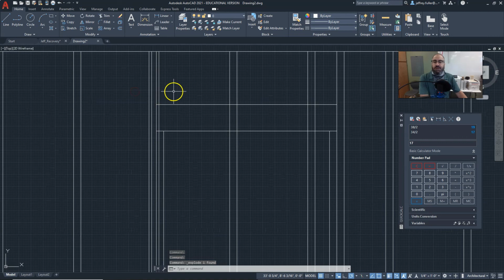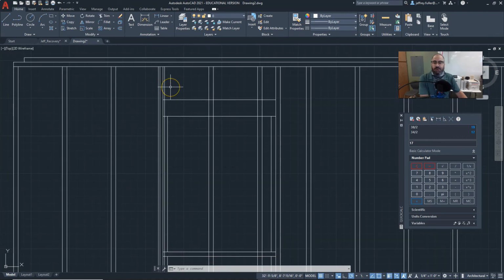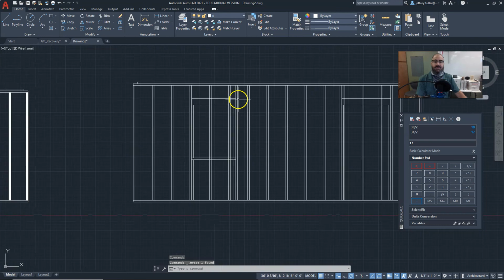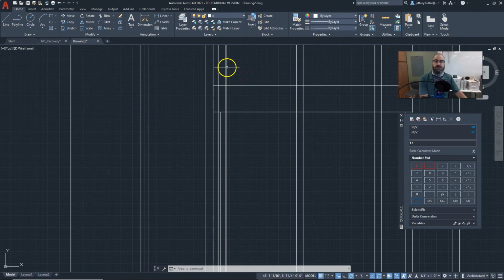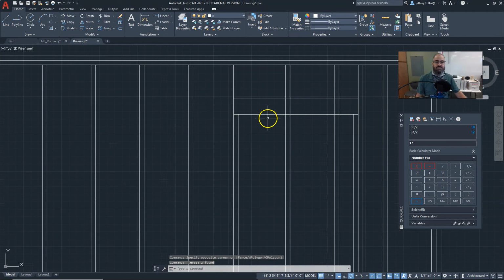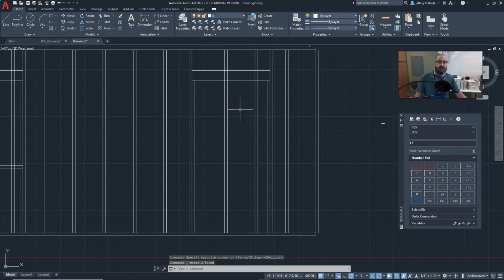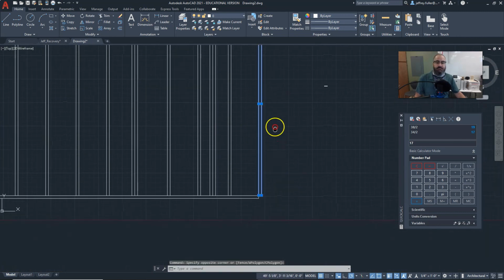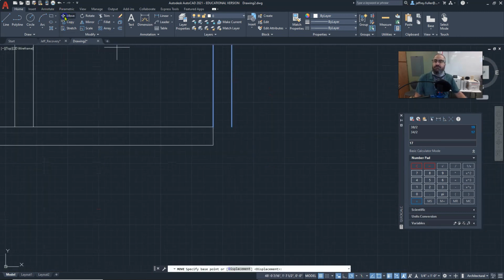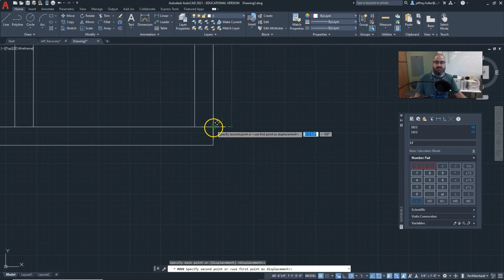All right, and in here I got to be real careful. Some of these overlapping studs I want to take a real close look at before I delete them. Okay, that one was overlapping, so I deleted it. Let's see if there are any other overlapping ones, maybe right here. This one is an overlapping stud. Okay, right there. All right, now there are some other studs that are in the way. This stud right here, I'm just going to select it, click the Move tool, select this as my base point, and then move it right over here and snap to that corner.